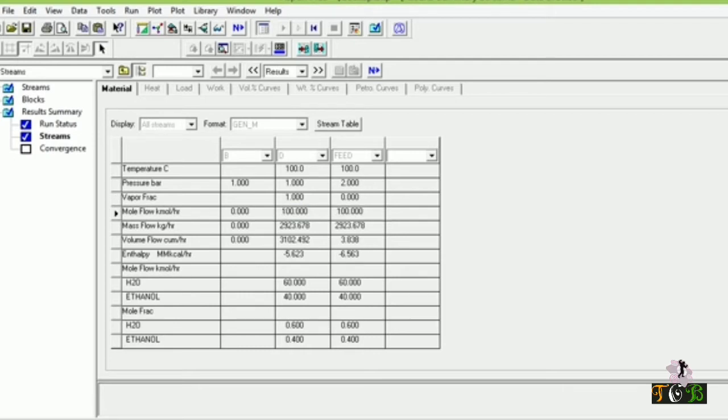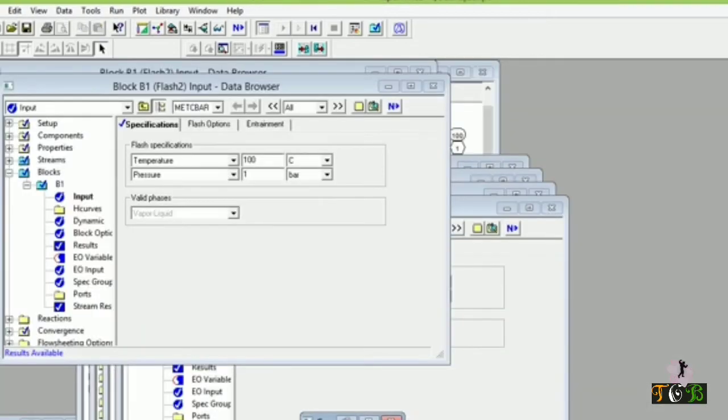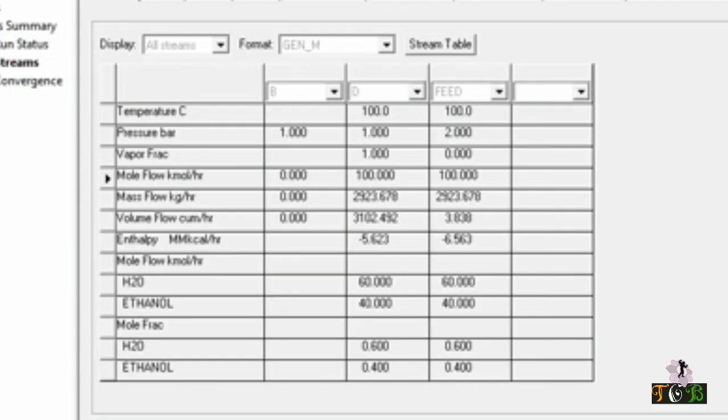So it tells us that there should be a range of pressure. If you reduce beyond it, there will be no separation. Then we have to ask ourselves how to find this range. In Aspen Plus we can also draw the PXY data. In the previous video we talked about the TXY diagram, and with the help of experimental data we can also draw the PXY diagram, where P is the pressure. So we can find the range in which we should do the pressure drop such that we get liquid and vapor. Otherwise we will vaporize all the liquid, and the flash operation will not happen.